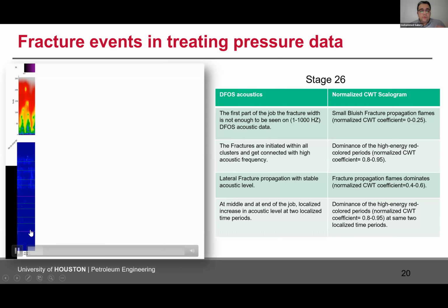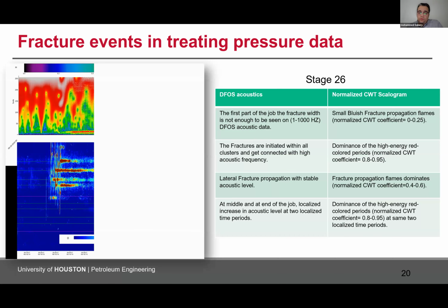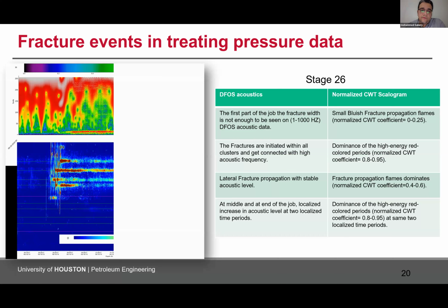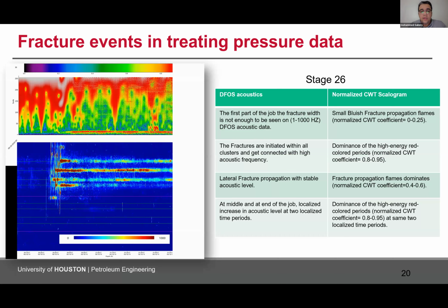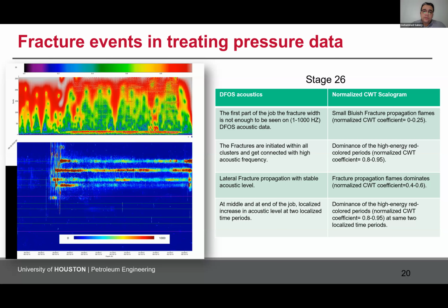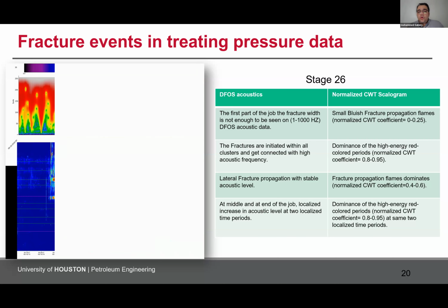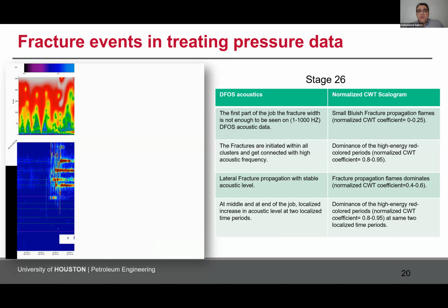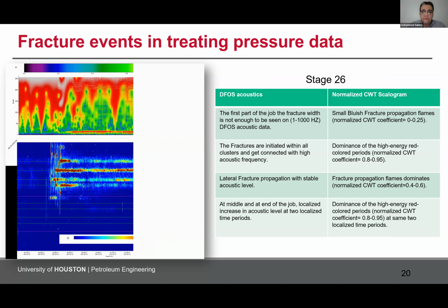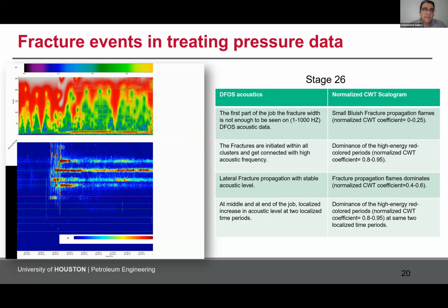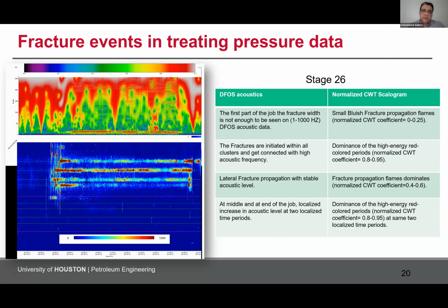And this is the video again, comparing the signature that we see on the scalogram with what the distributed fiber optic sensing acoustic data measure downhole. So we get this information based on free data, which is the treating pressure, with no cost added to the job, to get this fracture event detection. And this can be done in real time, through practical Python scripts. It took no time with the current